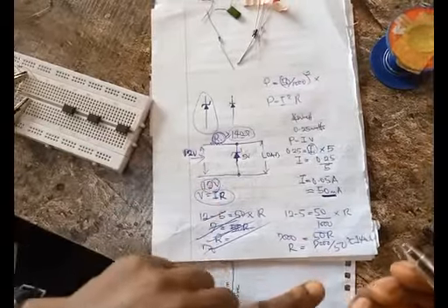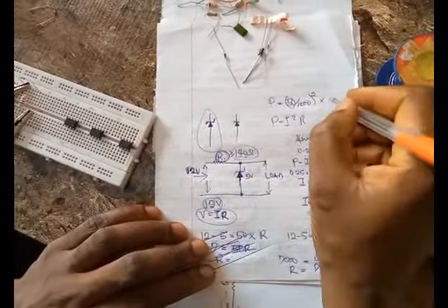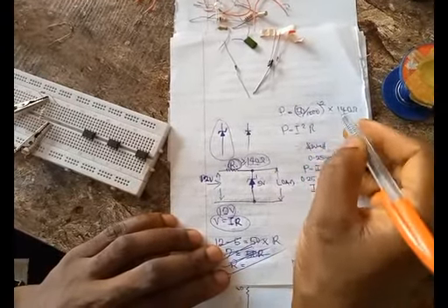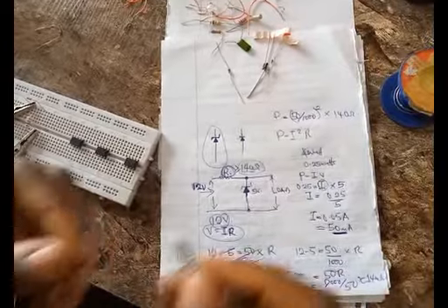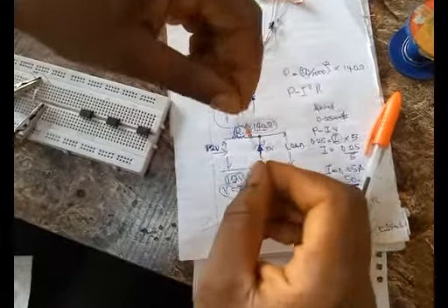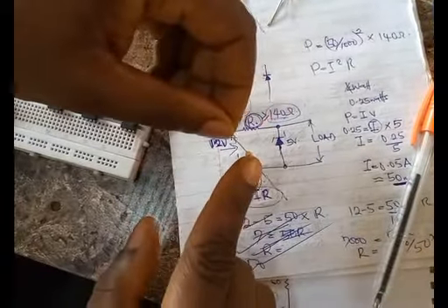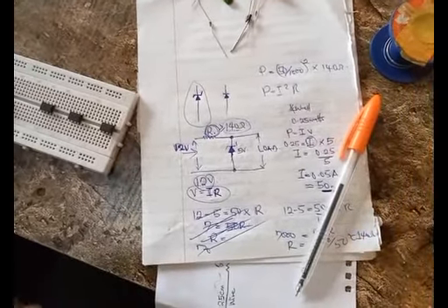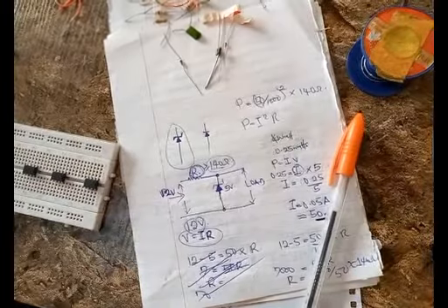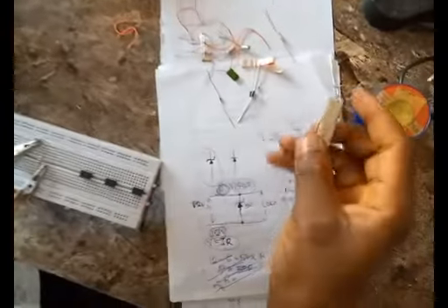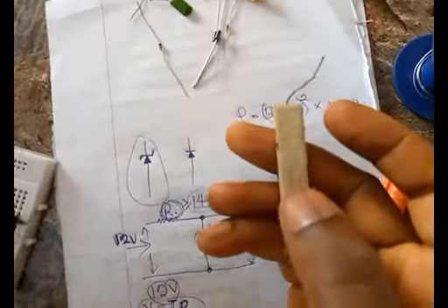We calculated for 140 ohms. So let's multiply this. This would give us the power rating of the resistor we use. Remember, resistors have different power ratings. The ones I'm using for the example are half-watt resistors. There are many other resistors with different power ratings. Let me show you one so you can understand what I'm saying. For example, this is another resistor, but this is a 10 watts resistor.